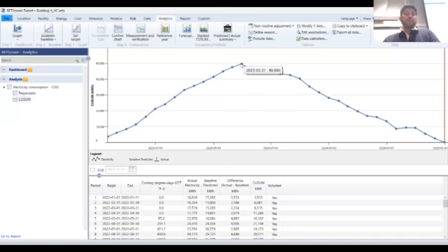So you see, I go up till March of 2023 and it starts going down. So I have a certain idea that that's when a certain retrofit may have happened, and that's when I start seeing savings. There's another dip somewhere around here, and it keeps going down. So I know that something happened in 2023, and it kept going down. This is your overall regression analysis. This is only to understand where I need to stop my baseline at. So I'm going to create another baseline.